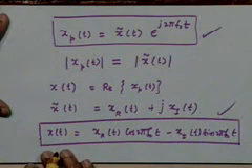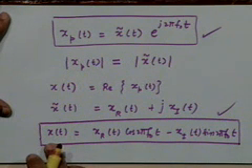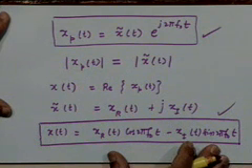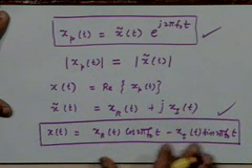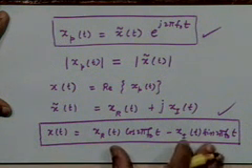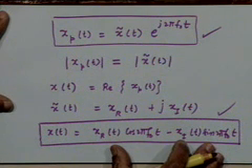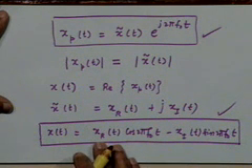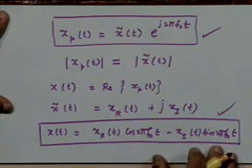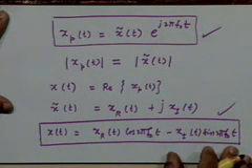So what do you find here? That the original bandpass signal x of t can be given a representation in this most general form, where it could be considered as the sum of two product terms. One product term is of the kind x_R(t) cosine 2 pi f naught t, the other product term is x_I(t) sine 2 pi f naught t.